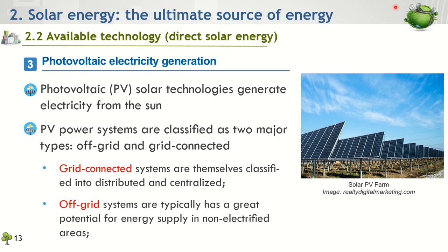So moving on to the photovoltaic electricity generation technology, or shortly called PV technology. Just like what it is called, the PV system generates electricity from sunlight or photon energy through the photovoltaic effect. This system is generally composed of solar panels for absorbing and converting sunlight into electricity, a solar inverter for converting the output electric current, and several other accessories for storing and distributing the power.